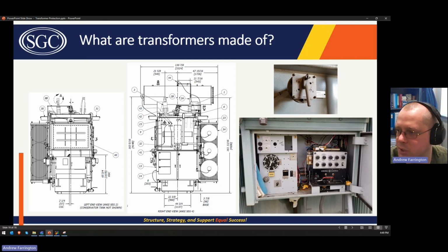And then this is a picture of a load tap changer controller. So this, like I said, is measuring the voltage somewhere on the low side of the transformer, and then these dials are setting like the bandwidth. So say you want to keep the voltage at your customers at 120 volts.